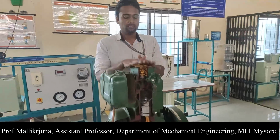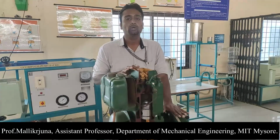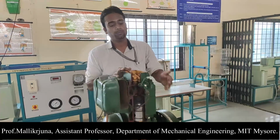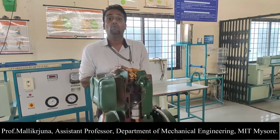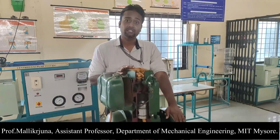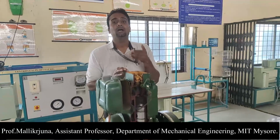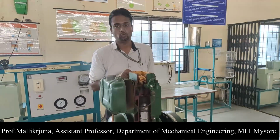So now in this experiment we are not burning any fuel over here, but we need to rotate the flywheel. I mean we need to rotate the crankshaft, thereby we will be giving the reciprocating motion to the piston. For that purpose we need to manually provide the energy to the flywheel so that I can look onto the opening and closing of valves for various strokes.